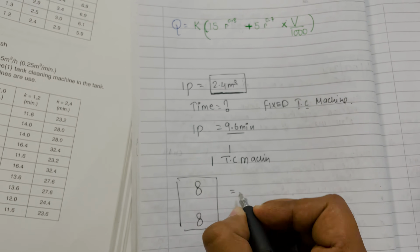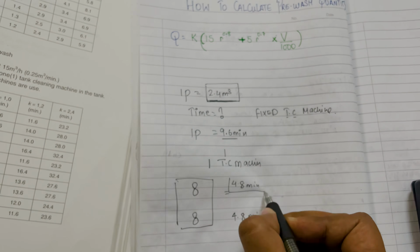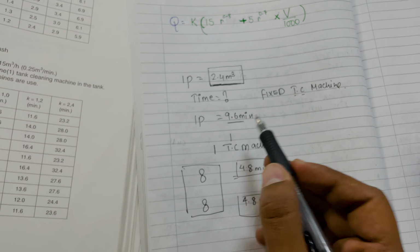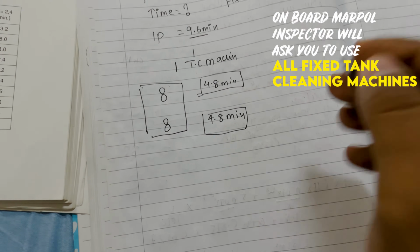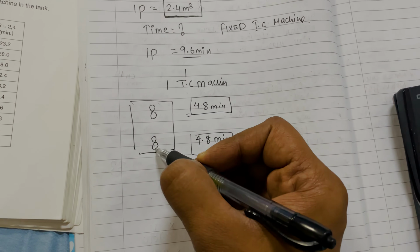So this 9.6 minutes, in this particular case, will become 4.8 minutes if I use 2 tank cleaning machines. Keep an eye on this, because if you have 2 tank cleaning machines in a tanker ship, your Marpol inspector will definitely ask you to use both the tank cleaning machines, because one tank cleaning machine will not be enough to cover the whole tank area.